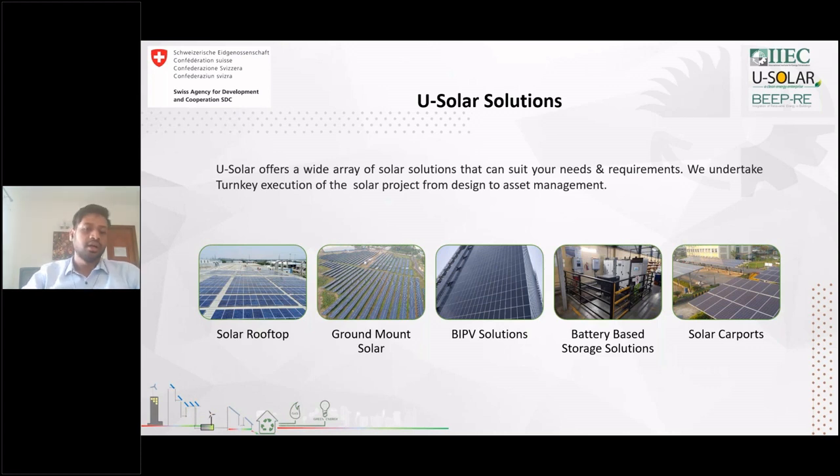With this, the next type of technology is called a battery-based storage solution. A battery-based storage solution is where you integrate the power generated by solar with a battery backup. Basically, solar generating potential is usually available only during the day. Your peak generation occurs for 3 to 4 hours a day, and the entire generation of the plant will be around 8 hours per day. So we capture this peak generation and utilize it in non-generating hours.